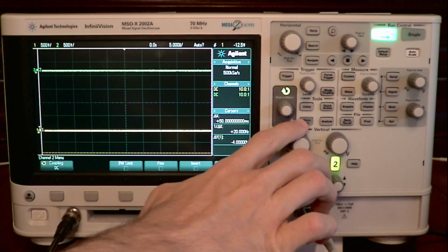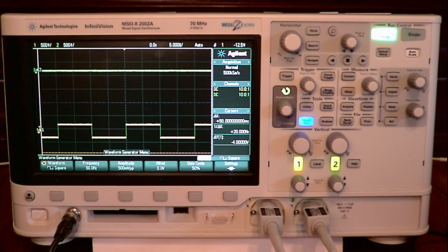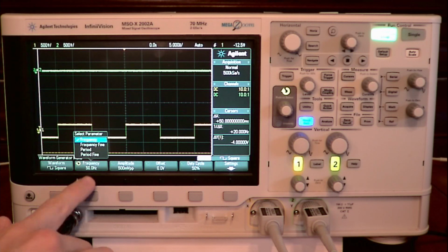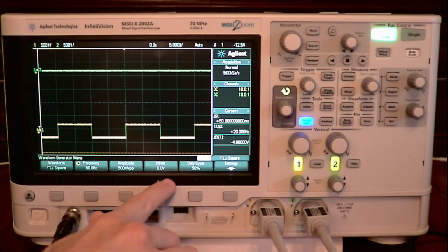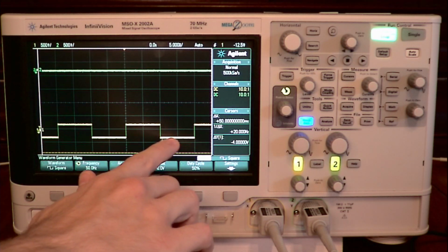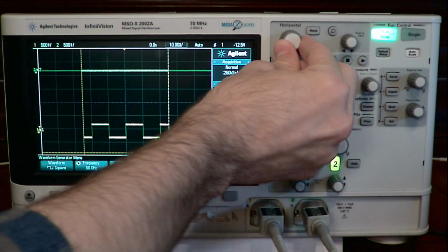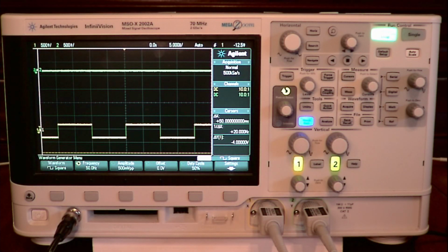Now from here, we should turn on our function generator, which again in this case is built into the oscilloscope. So we press this button, and we will see the waveform appear on channel 1 corresponding to the input. We can see it set to a square wave, to a frequency of 50 Hz. The amplitude is set to half a volt peak to peak, there's no offset, and the duty cycle is 50%. Depending on how you have your scope set up, you might need to adjust the horizontal scale so that we can clearly see the waveform on the screen. So if we adjust that back and forth, we may want to leave it at a setting where we can see one or more periods of the oscillation on the screen, like this.